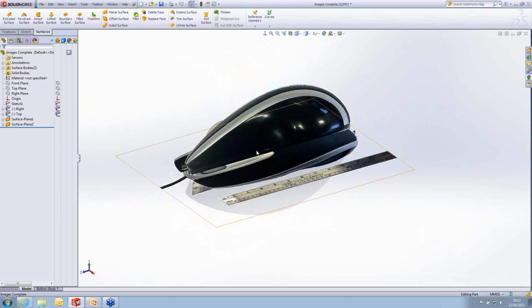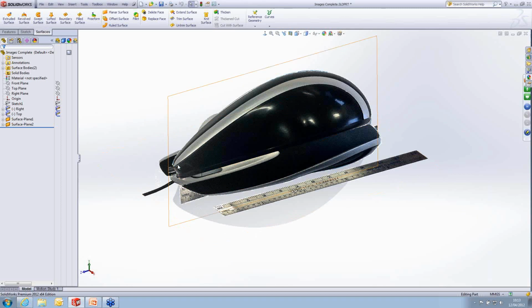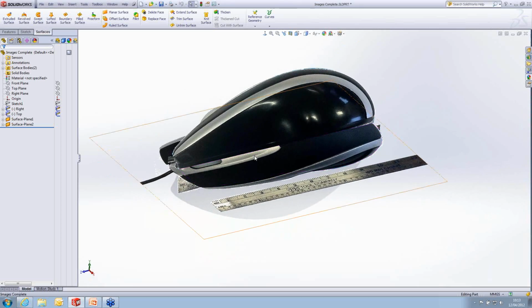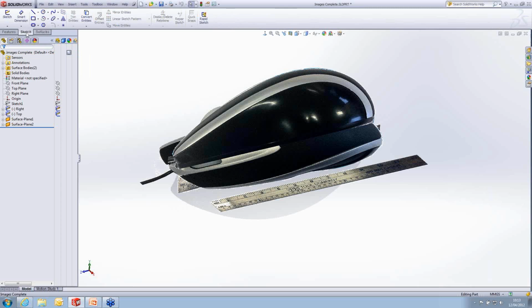Okay, the next change to make is to insert a sketch which matches this silver area around the edge of the model. And that's actually flowing in several directions. It's flowing in sort of three directions using the X, Y, and Z axis. So it's quite a complicated curve. And in order to create that, I'm going to use a 3D sketch tool. For those of you who haven't used that before, we can find that by dropping down under the sketch to find 3D sketch.